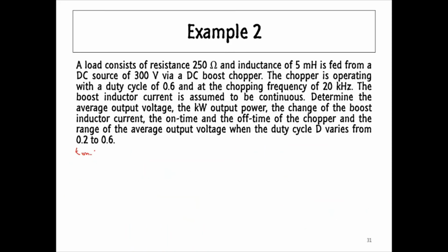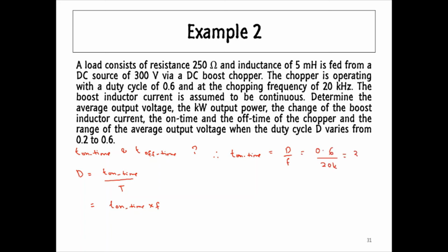Next, based on the duty cycle, we can calculate the turn on time and the turn off time of the converter. You will calculate both parameters using the duty cycle and the switching frequency.